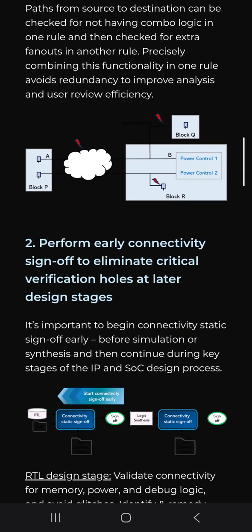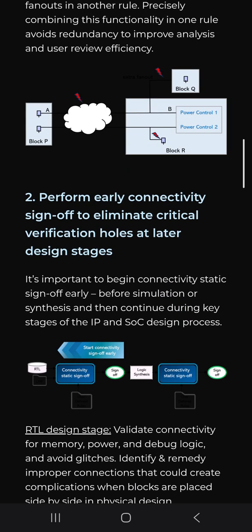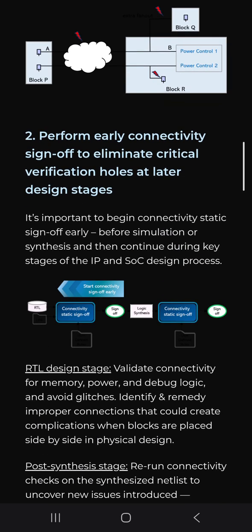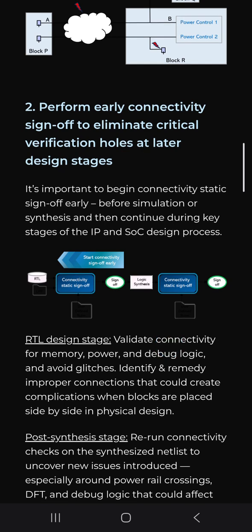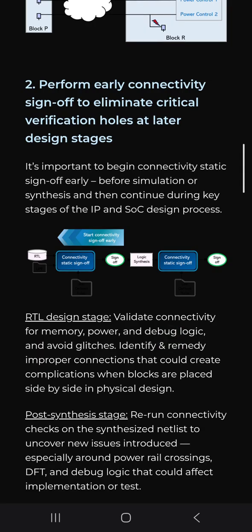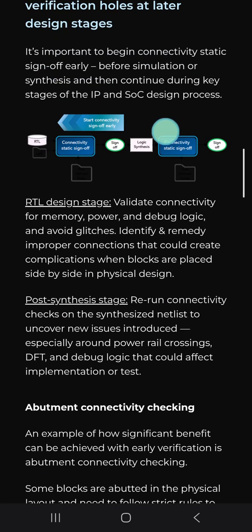2. Perform early connectivity sign-off to eliminate critical verification holes at later design stages. It's important to begin connectivity static sign-off early, before simulation or synthesis, then continue during the key stages of the IP and SoC design process.